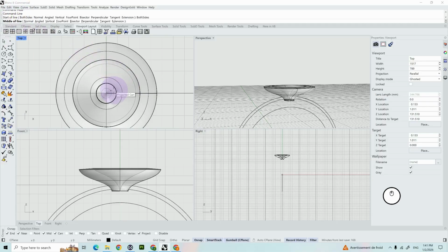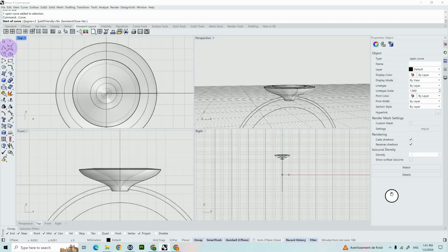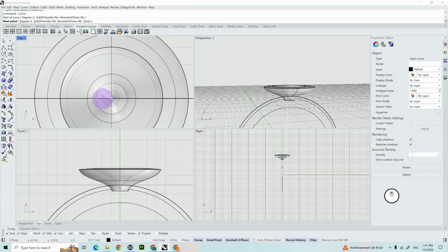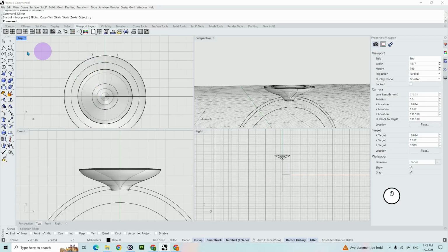Select both sides. The middle of the line will be 0, and for the length of it, let's make it 0.5 and snap it horizontally like that. And now I'm going to take my curved line, snap at the end of our curve, and simply create a curved line like that. I'm going to mirror this on the other side and simply close the open area, just like so.